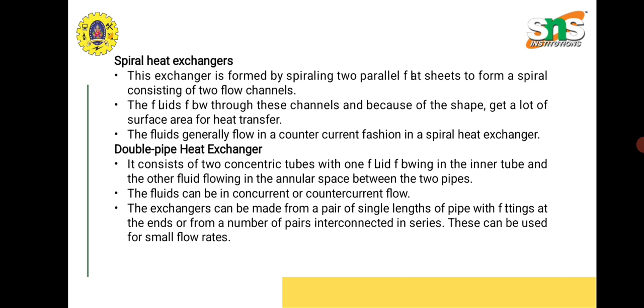Double pipe heat exchanger. It consists of two concentric tubes with one fluid flowing in the inner tube and the other fluid flowing in the annular space between the pipes. The fluid can be in co-current or counter-current flow.